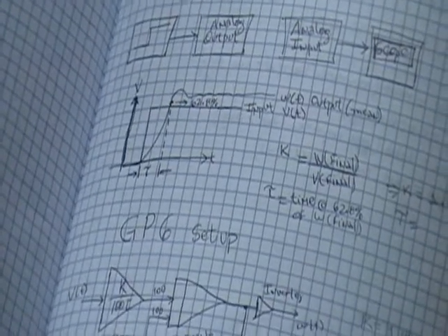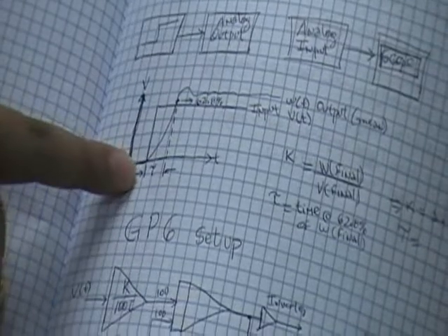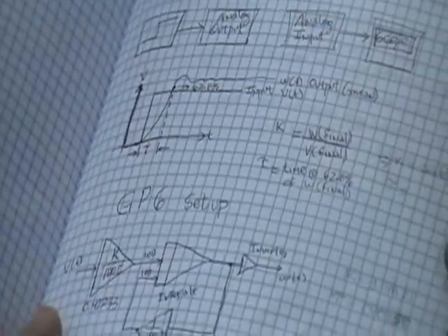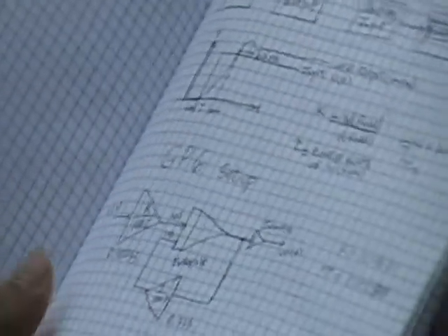Note that you have to calculate the time constant from the time the step was applied, not from zero, okay? Because you may make mistakes over there.